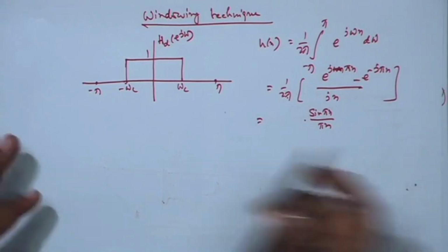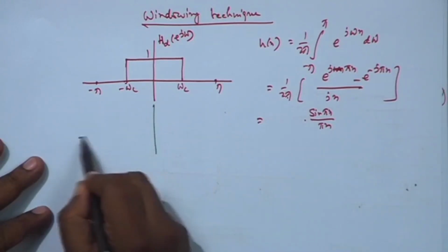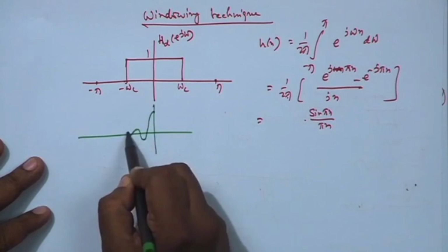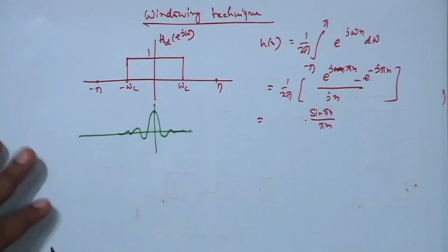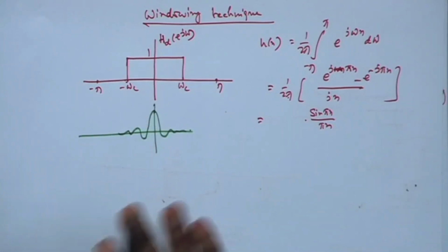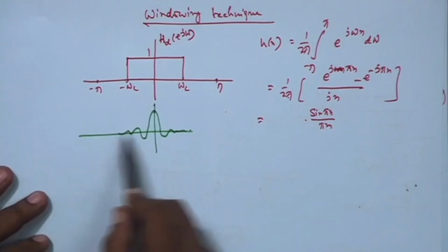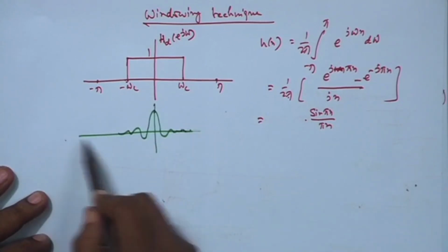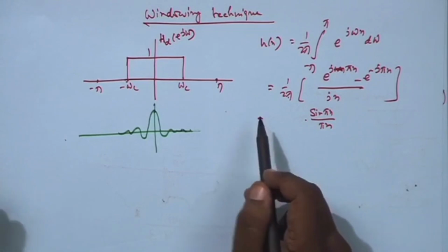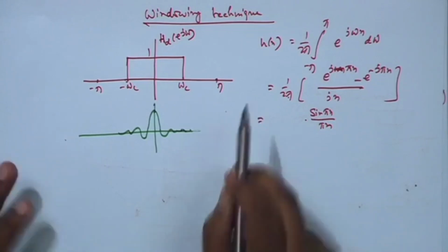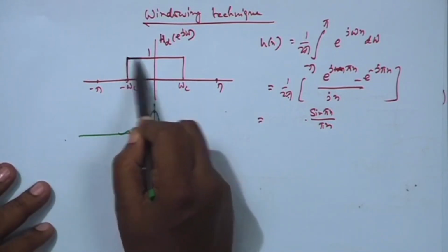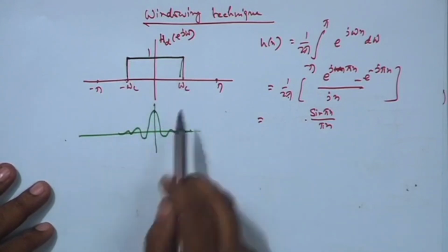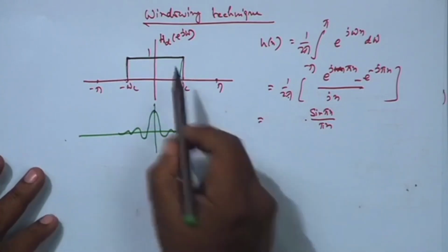So, you see this is going in both directions, sinc function, all right. So, it is a non-causal filter and IIR theoretically going up to infinity, minus infinity, infinity. Okay. That is because if you have got such abrupt discontinuities, you cannot realize it by using just a few filter coefficients.